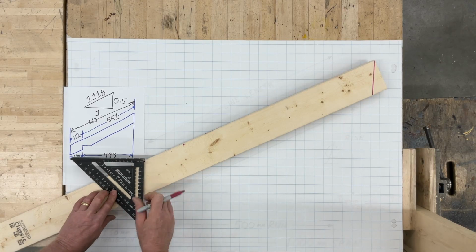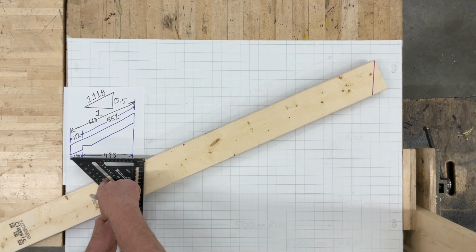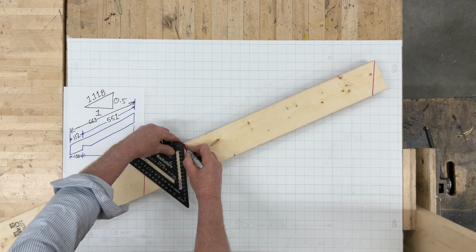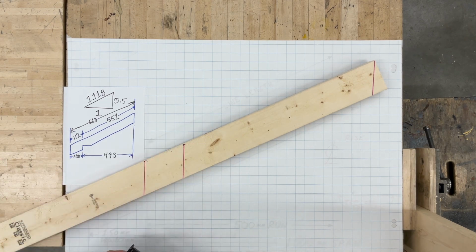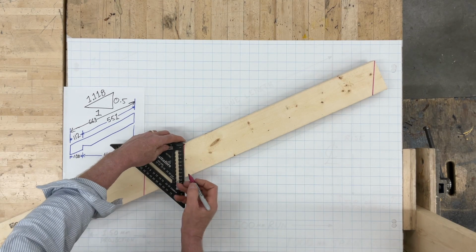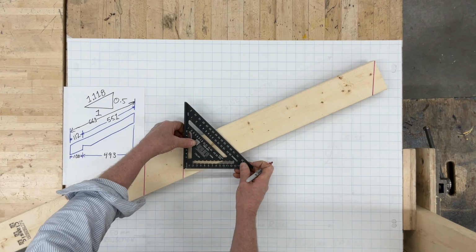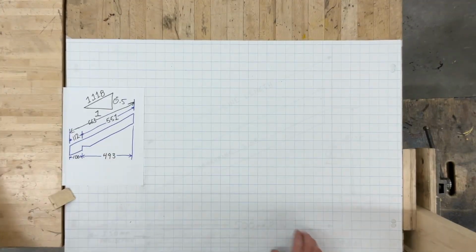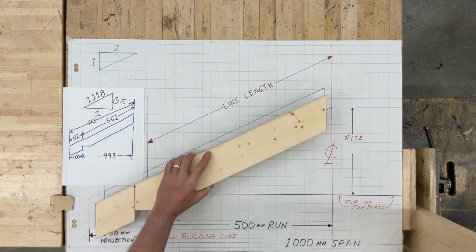From your tick marks, use your speed square to mark these plumb cuts for a 5 to 10 slope. Then, measure for the appropriate height of your seat cut and use your square to draw your seat cut 90 degrees to the plumb cut line. Cut out your rafter and check it for fit before making the rest.